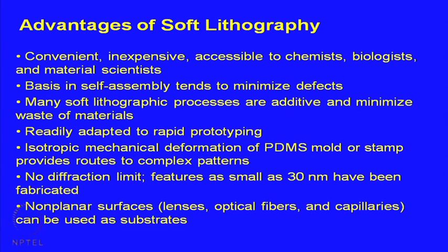So it's convenient, inexpensive, accessible to almost everyone, most importantly people who are non-experts in lithography. The basis of most of the methods is self-assembly of some sort or the other, which tends to minimize defects, rather than mechanical processes or embossing like photolithography, for example, because here to a large extent you rely on pattern replication through forces like capillarity, van der Waals force, self-assembly, etc. Many of the soft lithographic processes are additive and therefore minimize the waste of material.